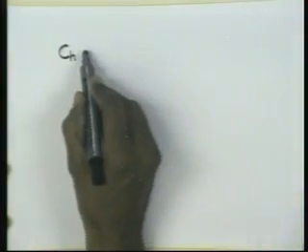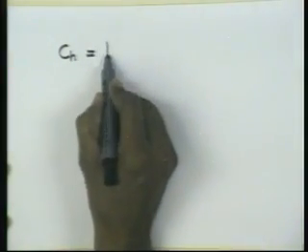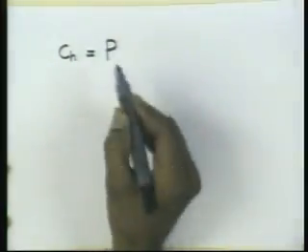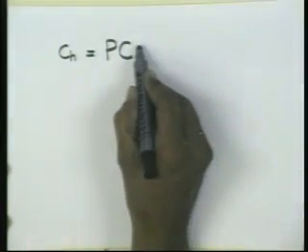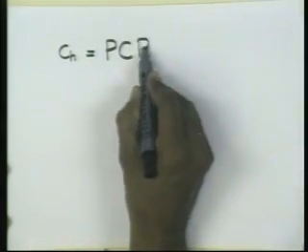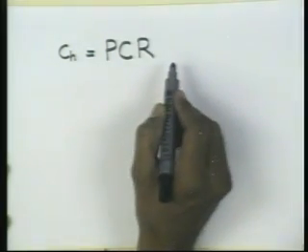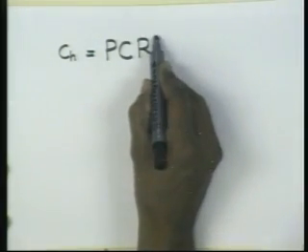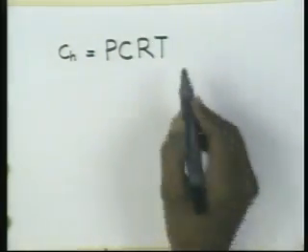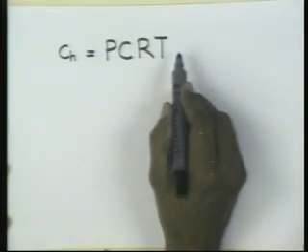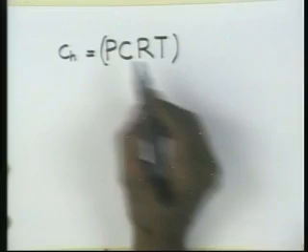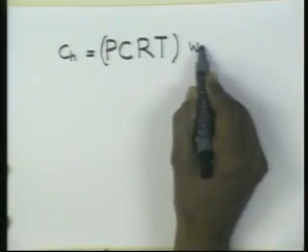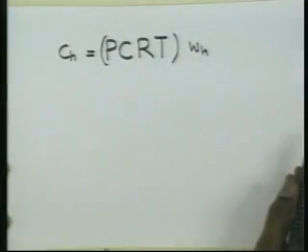We had to multiply a number of transforms: the perspective transformation, the gimbal offset, the rotation, which can be clubbed together, the pan and a tilt, and then the translation of the global axis to the gimbal center. All this has to be multiplied to the world homogeneous coordinates, right.